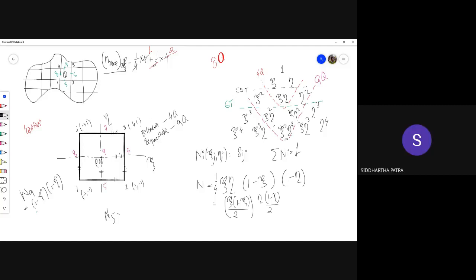Achha, now think of the 9-noded quad element. Let's put the central node number 9. How many elements is this 9th node shared with?